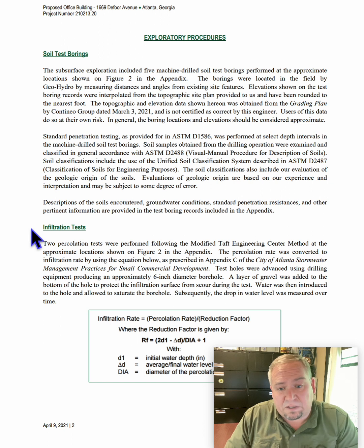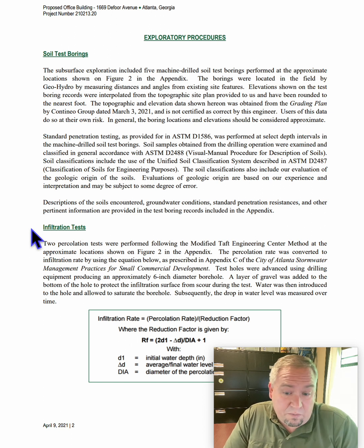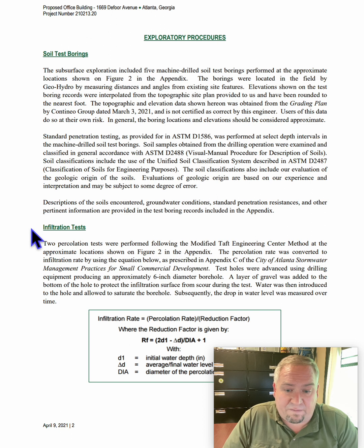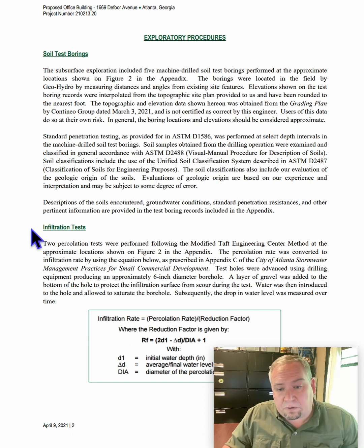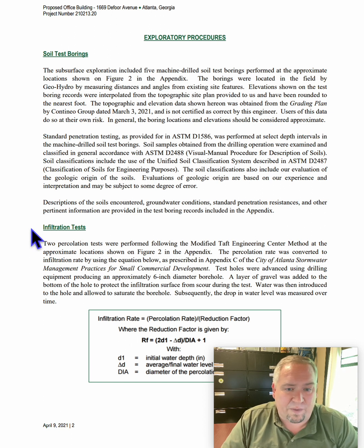It can be indicators. Also, if you're building a stormwater management plan and these soils don't percolate very well, you may have to oversize your detention pond to accommodate that. If you get back-to-back storms and it fills up but isn't percolating down through the soil, they'll have to accommodate that so it doesn't overwhelm it.